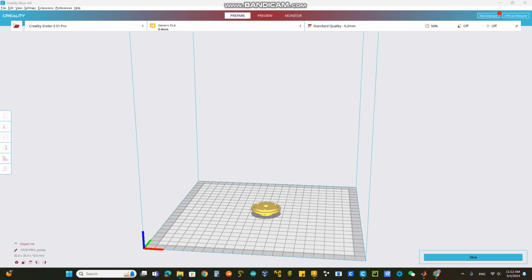If you just left click on your model, you will find here in the left, in the first tab, Move. You can move this model. For example, as we see here, x represents the x-axis, y the y-axis and this the z-axis. For example, if I want to move this model in x by 20 millimeters and press, if I want to move it in y 20 millimeters, and so on. So in this tab you can move your model, and this is a good feature.